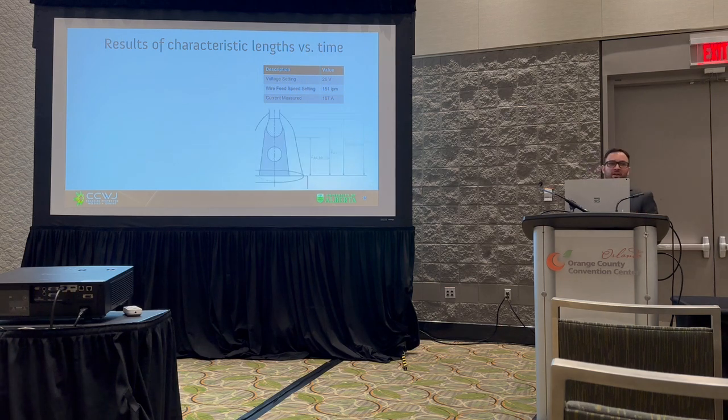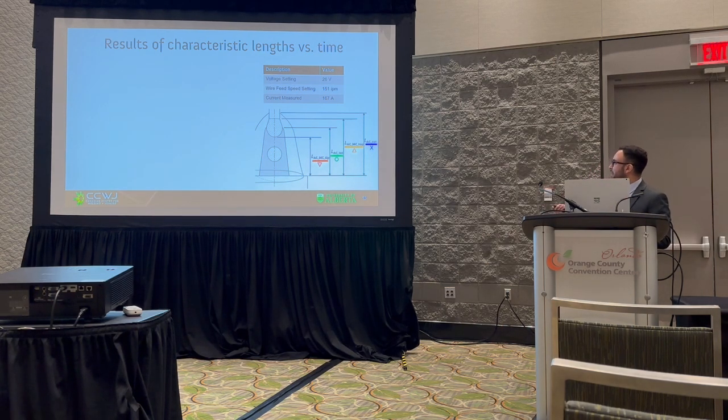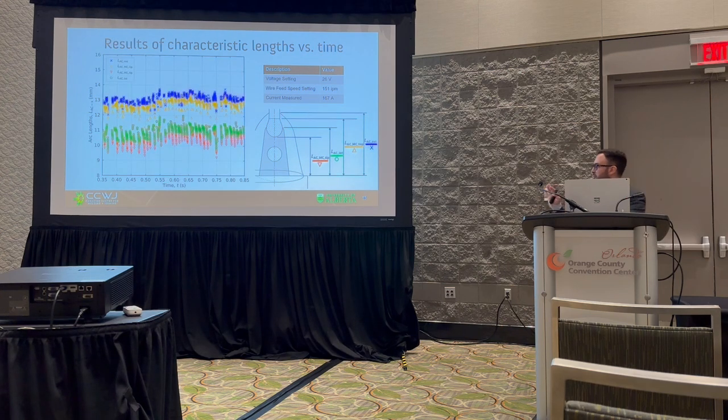Okay. Now, when we discussed grabbing massive amounts of data to get a true representation, I want to just highlight here each one of these markers, just recapping: the tip, the length of the arc to the tip, to the internal arc, which is the metal vapors, to the top of the molten consumable, and to the external arc. If you plot this just for, let's say, half a second, you can get an appreciation for what's actually happening, how much changes actually occur during these droplet cycles.